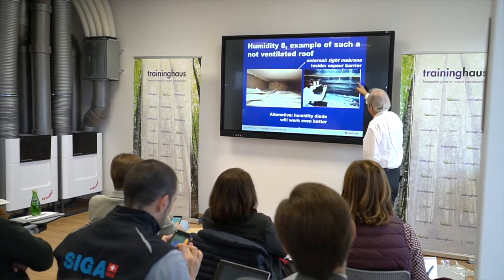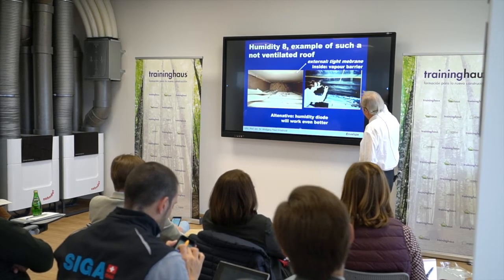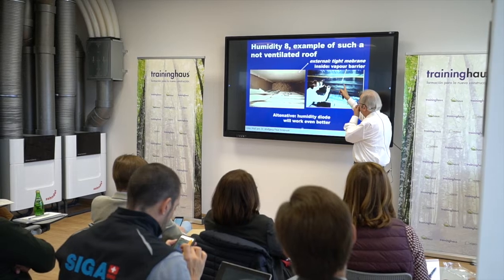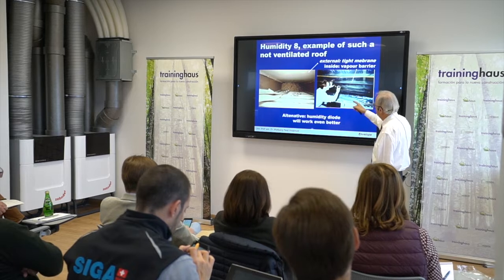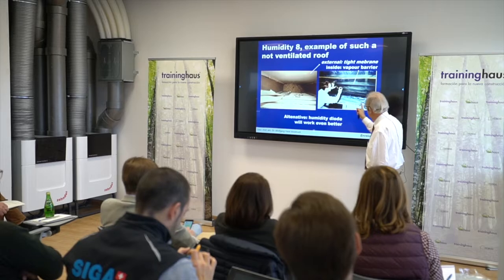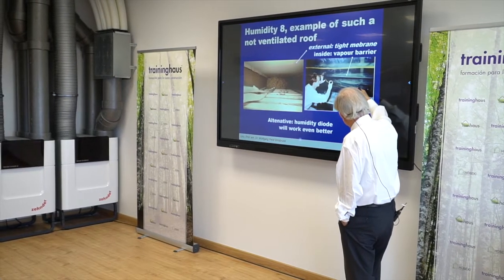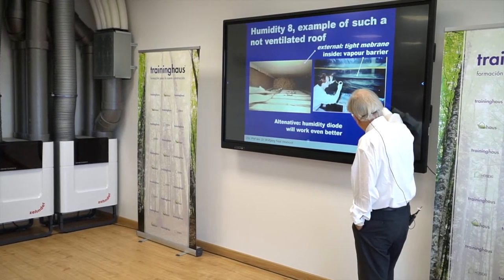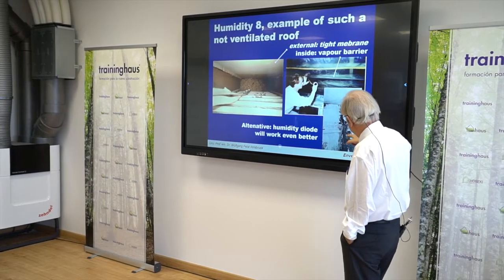This is the airtight membrane we used in this construction. We thought that there might be a problem with the little holes we get by the nailing of it, but it's so tiny it wouldn't be important, but we kept some caution here. That was the very first time we did it. This is how the airtight connection was made to the plaster. I'll show that in more detail later on. This part of the membrane will be covered by the plaster. That's the way it has been done. This is the covering of the membrane by the plaster.